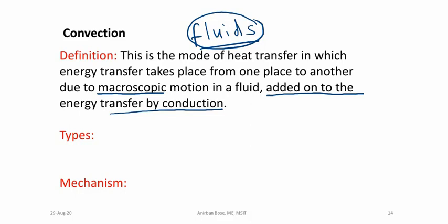So in the word convection, there are two parts. One is conduction in the fluid. Along with that there is a part that is heat transfer because of the bulk motion of the fluid, which has been referred to as the macroscopic motion of the fluid. It is not the motion taking place at the microscopic level. It is the bulk motion of the fluid.